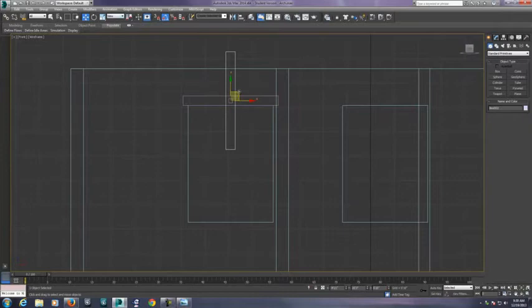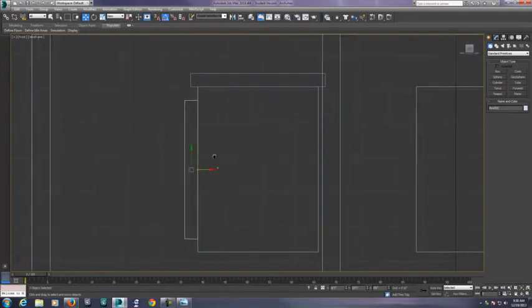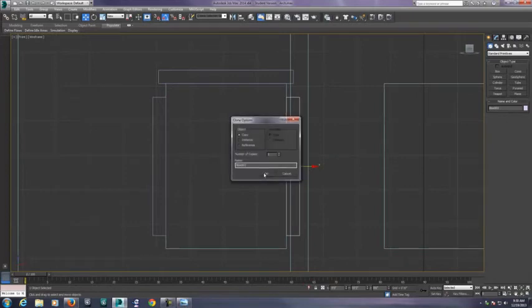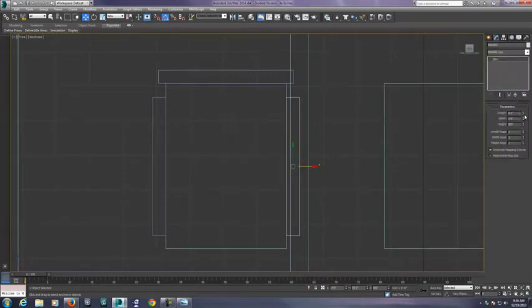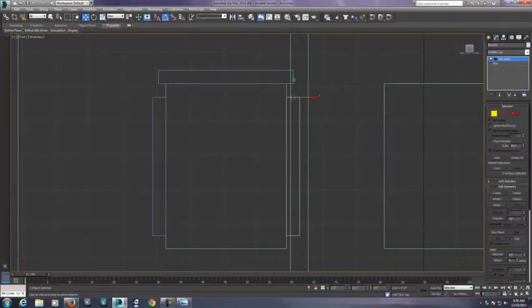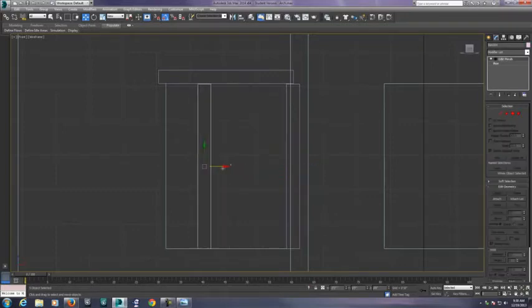and move it over to the side of the window here, I am in fact going to have to make it wider. And again, it's just kind of aligning it here with the exact window. I'm going to go ahead into my scale, and you know what, it might even be better just to go into Edit Mesh and grab the vertices and move them where you need them. So we'll pull them like this, kind of bring them down here, and maybe just duplicate that since now I've got it scaled the same size.